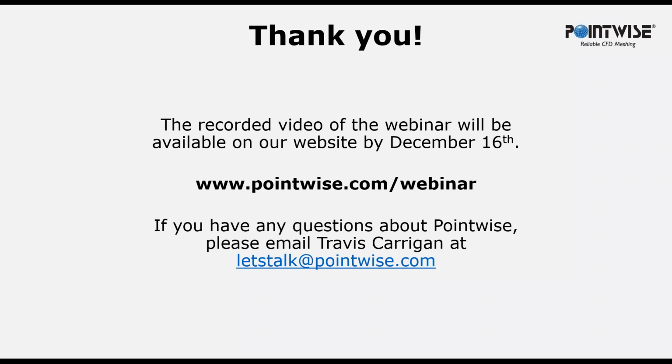I feel like Travis covered this a good bit when he went over the comparison of using a triangular surface mesh and growing tets or prisms off of it versus creating a quad dominant mesh and growing it directly, or having Pointwise push quads down to the surface. But this also ties into my answer for the first question, which is you should see improvements in accuracy and convergence from your solver from moving to a quad dominant and essentially not quite a hex dominant volume mesh, or at least hex is in the boundary layer. So there's definitely a benefit to go ahead and moving to it.